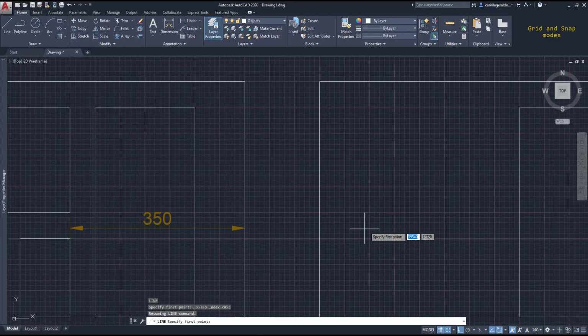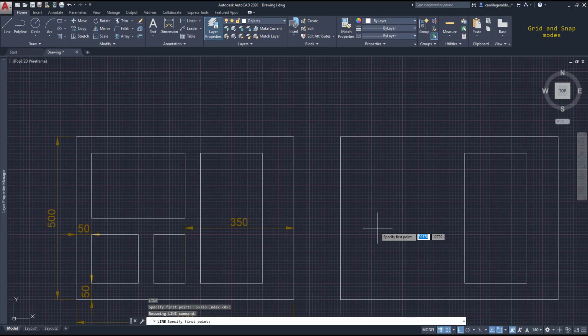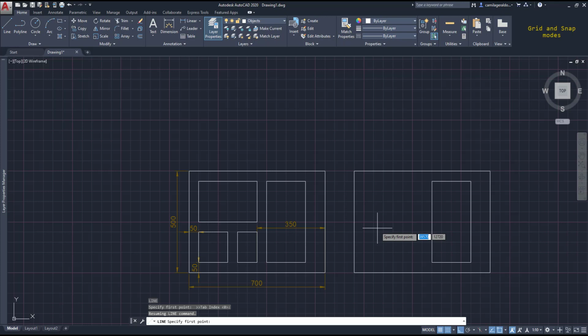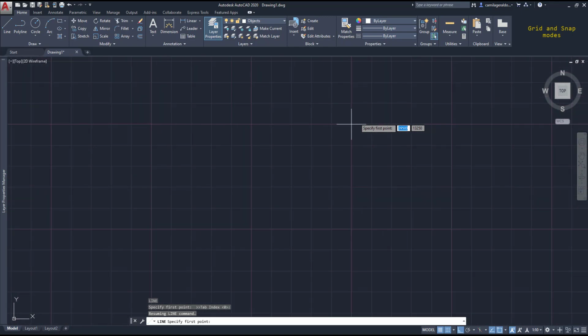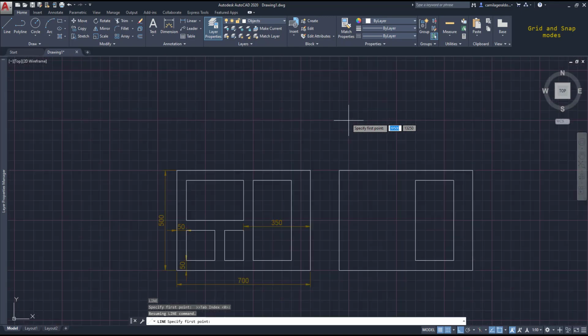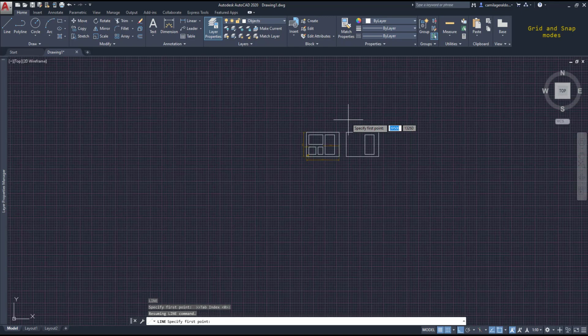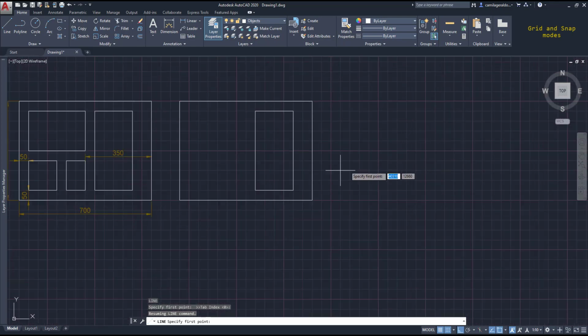If I'm zooming out the workspace, at one point the grid resizes, in a way that the lines won't get that close. We couldn't see anything if that would happen. This means that at this moment the spacing here is not what we put on the settings. Be careful, don't draw anything now. Always draw in the maximum zoom. And in the case that you want to draw bigger objects, simple, just change the spacing settings to bigger values.